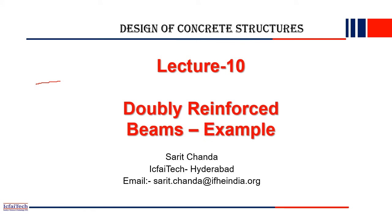If it is a rectangular beam, or any beam in that sense, it will have a certain B value. Similarly, it will have a certain D value. D is nothing but the effective depth. In the case of a singly reinforced section, reinforcement is provided only on one side, at the bottom if the section is at the midspan. So these bars are provided at the bottom.